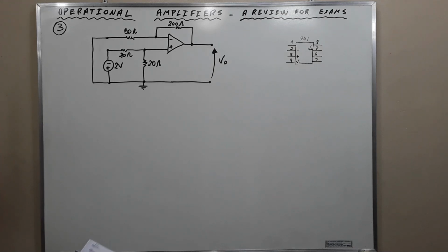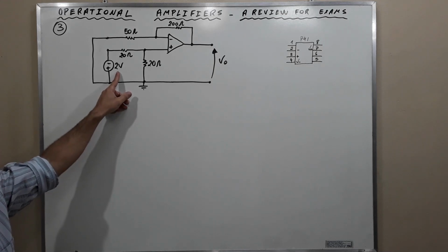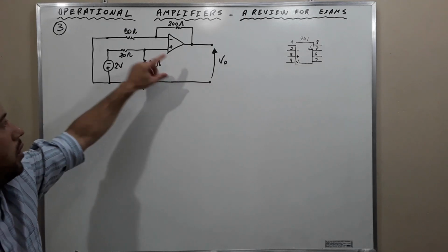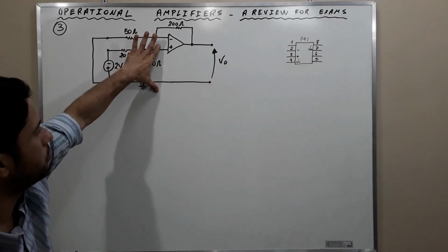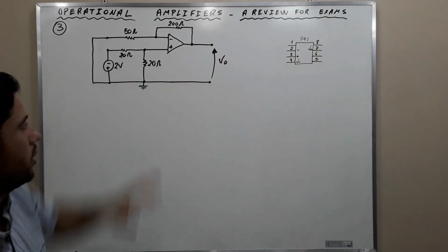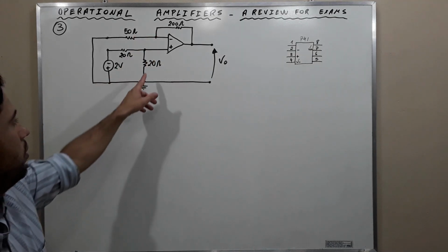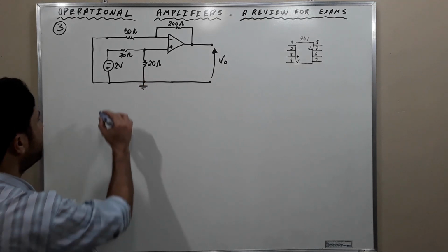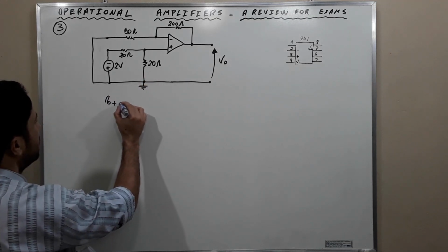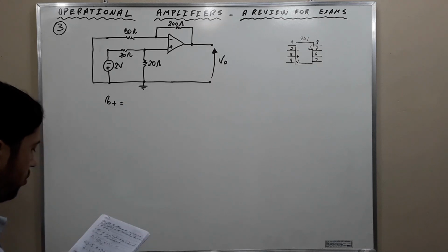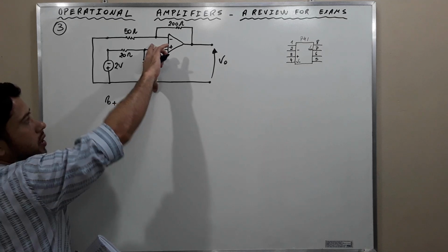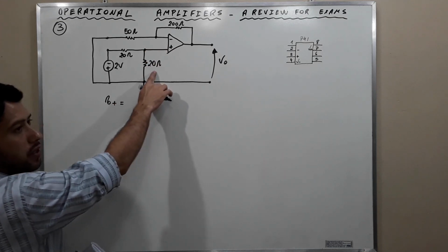Okay? We do not want this voltage here because it is not being directly applied here. We want the voltage from here to ground. Okay? And to do this, we need to apply the voltage divider rule here. So V plus is equal to, okay, the voltage is going to be here. So we are going to take this as a reference.